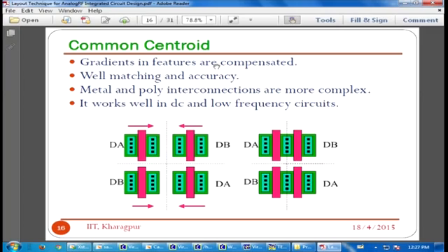So the common centroid architecture which you have picked for analog design sometimes looks very fancy, but in RF design you take care of the routing, the total path. If the interconnect path length increases, that would introduce unnecessary parasitics to keep it in a centroid format. So then you have to make a little bit of compromise. Okay, so that's what is mentioned.